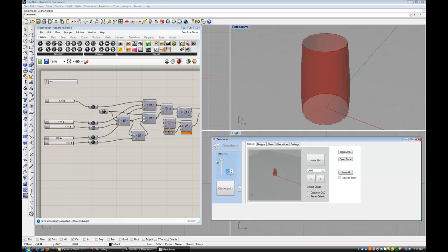And within Grasshopper, you're going to need to have the slider at 100% wild so that the number will slide between the full min and the full maximum numbers that you've set in the parameter. If you want to deal with the other percentages, the way it works is it will take the percentage of what the number is right now, so let's say 6.31, it finds 50% of that number and it creates a minimum that is 50% larger than the number and 50% smaller than the number.